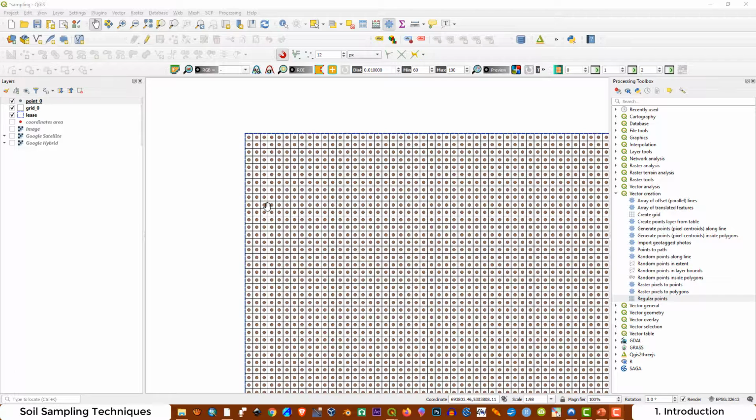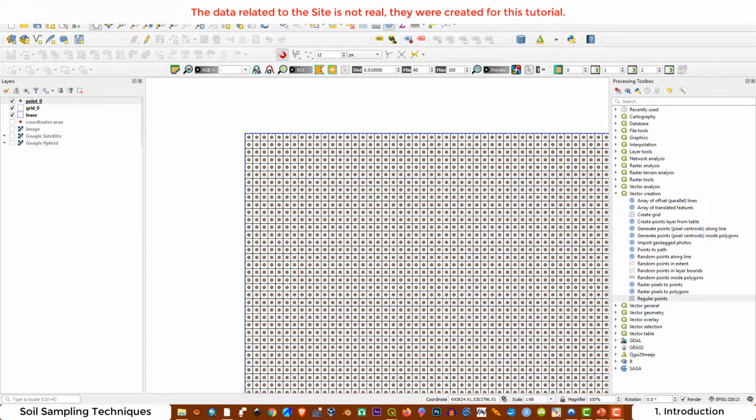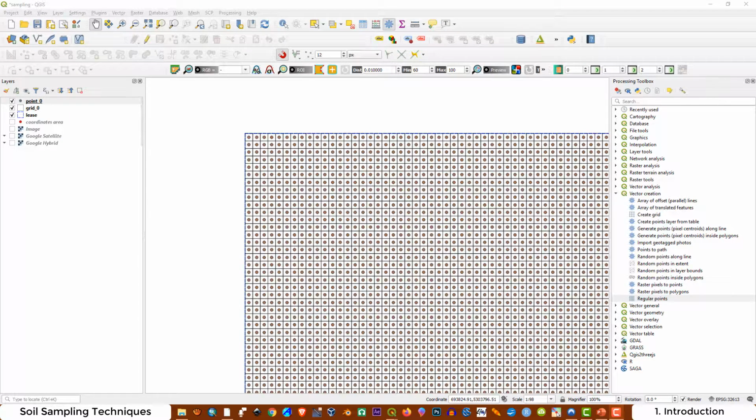That is very important, because each parameter has different behavior. Each parameter has its own characteristics, and is going to be distributed spatially in our site in a unique way. That's the reason why we have to adapt the population according to the parameter we want to analyze. For example, it's not the same to analyze pH or temperature or electroconductivity, right? Each of these parameters has a different gradient, and then we have to consider different kinds of populations.